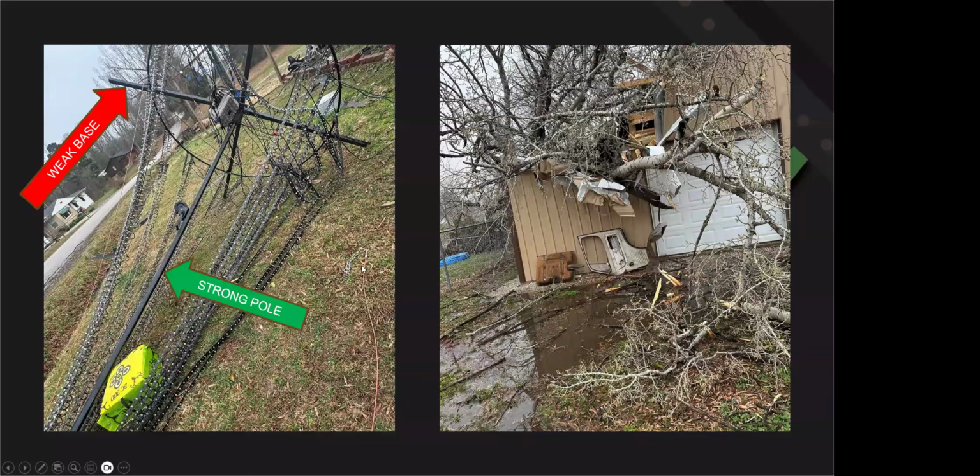Here you can also see where there were guy wires. They're slacked on this side. This one, I can't tell quite what it's connected to, if it caught something. But the fact that nothing here seems to have broken would say to me that the guy wires really didn't do their job, probably pulled out or broke somewhere that I can't see on here. So had they had better guy wires or a heavier, stronger anchor system, it may have allowed the tree to survive.